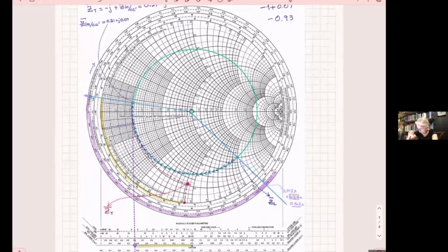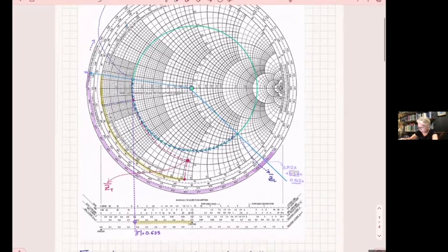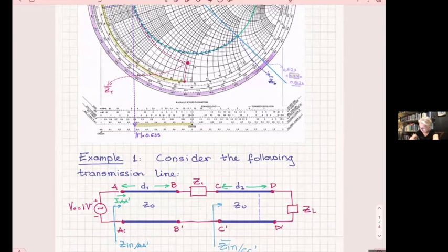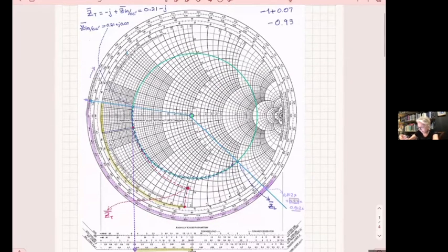So here I am at a different, if you see ZT is off my green circle, which means I have a different circle to draw for this part of the line. My green circle was for this one, all right, the green circle. Now I have a different circle, which is this one, and I'm going to do it with red. So it's going to be the circle that has its center at the center of the Smith chart, but it goes around like this.